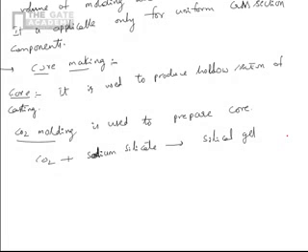Then remove the mold sand, and it acts as a core. The strength of CO2 molding is due to the chemical reaction between the CO2 and sodium silicate, and it does not last for a longer time.